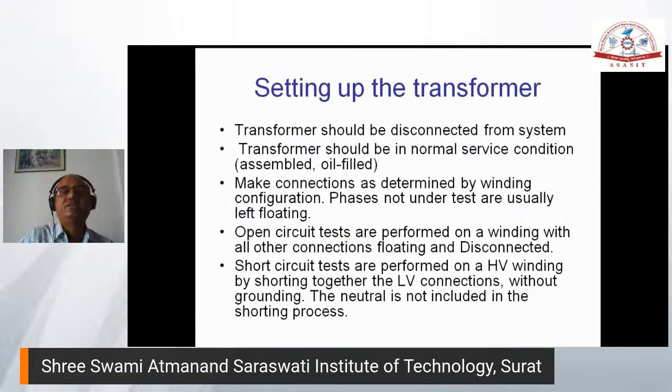So when we do the SFRA testing, it is normally done at lower voltages, but at a sweeping frequency. It is around 20 volt. Even if the transformer may be 132 kV, we use a low voltage, because impedance is not going to change with respect to the voltage, right? Whatever voltage is applied, the sensitivity of the measuring equipment should be adequate. That's the requirement.